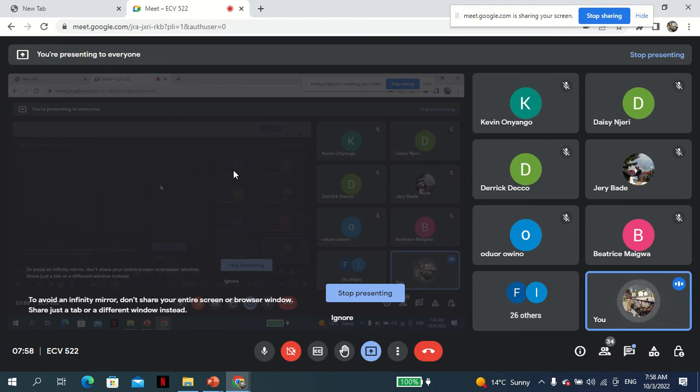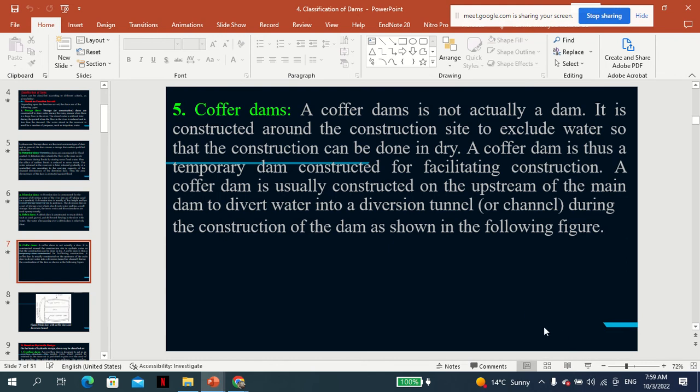the natural course of the river is not starved, because if you divert all the water from the natural course of the river, that would be a riparian illegality. Actually, it's a big issue because the riparian law does not allow that. So you still allow some amount of water in the natural course of the river, but you divert. So, for example, the Odino one is a diversion dam, in fact. The water goes through some place where we can get enough height to generate electricity. After that, the water is channeled back to the natural course of the river as well. So this is what we are saying, and that's a good examination question, I think.